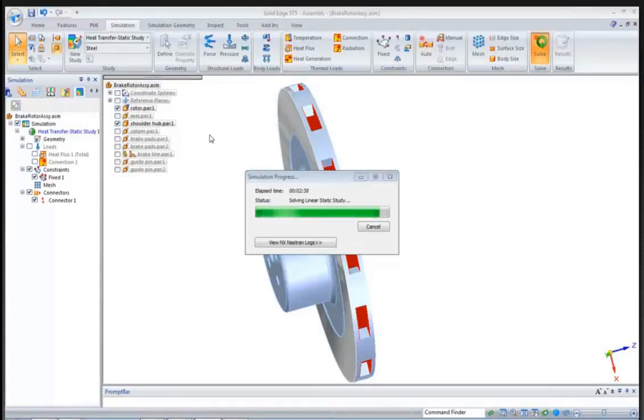The convection coefficient is not as easy to just look up. It's dependent on this material but it's also dependent on whatever fluid you have, and it's also dependent on the geometry. So you're going to have to spend a little more time researching what convection coefficient you want to use. Now, there are cases where people out there do a computational fluid dynamics study to find out what the convection coefficient is for a certain situation. They publish that out there. So you can go out on the internet and find a good value and use that. So it's just a little harder to figure out.